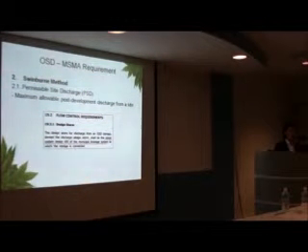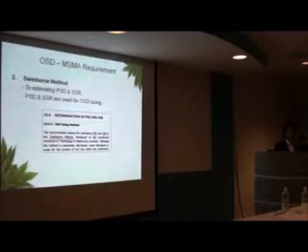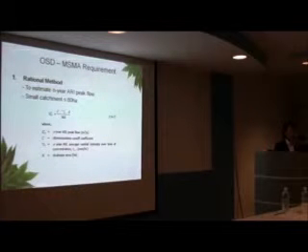Because to calculate Q, if we refer back to the previous formula, we need CIA. The I stands for rainfall intensity. The rainfall intensity depends on the frequency of the storm we choose. If we choose 2 years, 5 years, or 10 years, the higher the year of ARI, the heavier the rainstorm is.